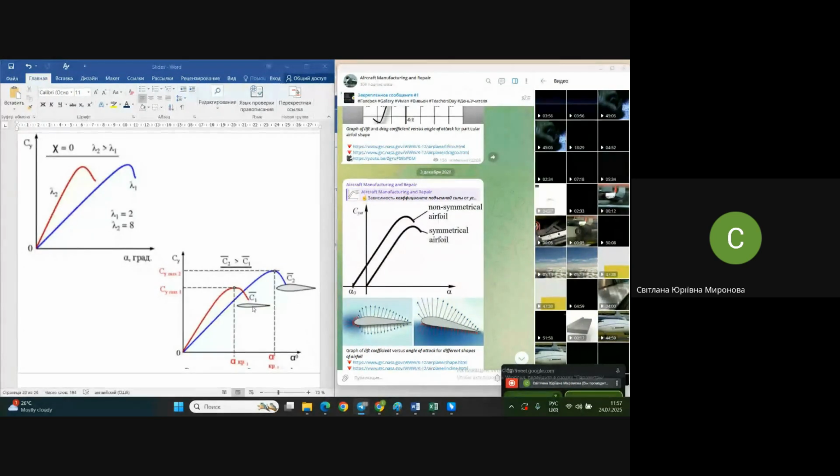You see, for thinner airfoils we have less efficient characteristics, in my opinion and in the opinion of those who operate airplanes, pilots. Yes, it's higher, it seems, at a rather low angle of attack, but it has a very low critical angle alpha. So it's more dangerous in this sense.